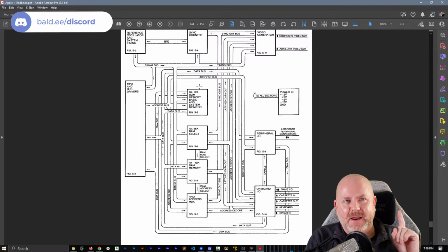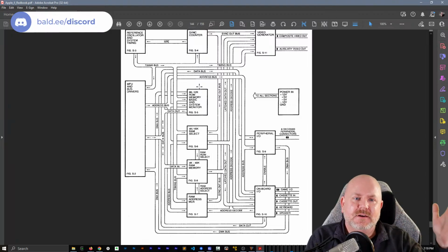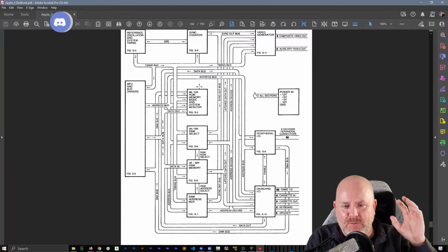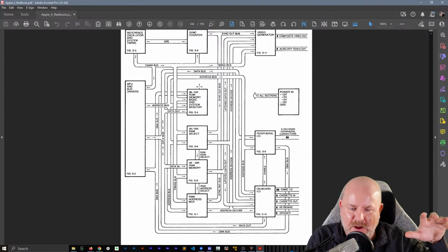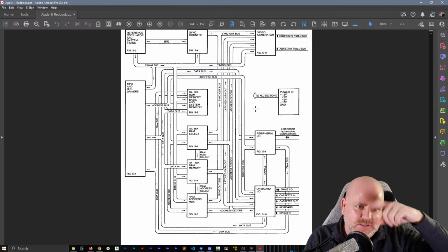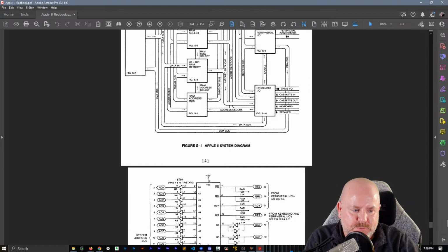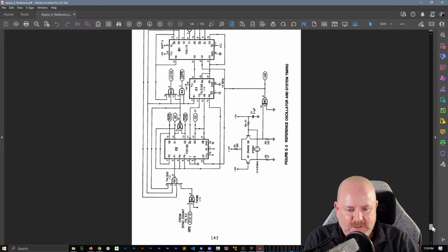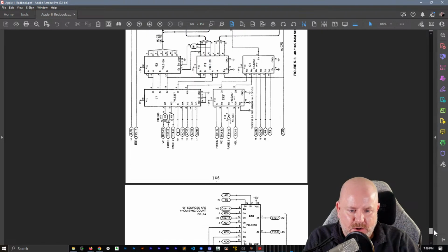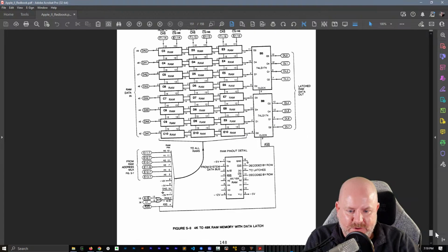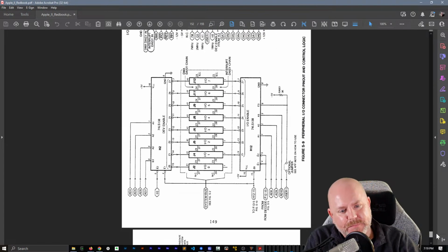But I think where I'm at is if we get the schematic to pass ERC, then we can blow away what we have and redo the top level. Because then it's just a matter of reconnecting things. But right now, we've got to fix these other problems, like these jumpers that are mislabeled. So that's where I'm at.